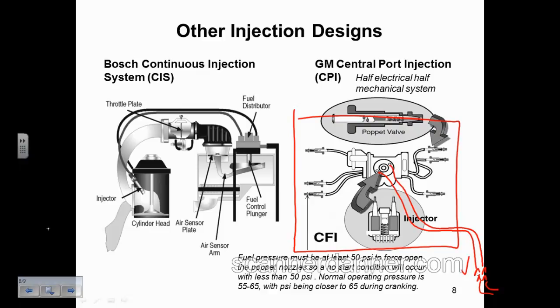What was the number I gave you guys? 30 to 65 on page 2. For the most part, you're talking 30 to 40 PSI is on average what I was familiar with on just about every multi-port injection system. So I had 49 pounds of pressure. Was I okay with that number?